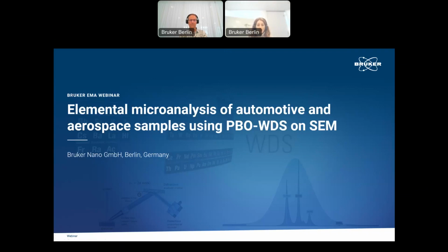In this webinar, we will review the advanced capabilities of WDS to support the development and quality assurance of materials used for the aerospace and automotive industries. We will explain how WDS is an essential analytical tool when analyzing light and trace elements and complementing the elemental distribution analysis by EDS. And why with a WDS detector with grazing incidence X-ray optics, we can enable measurements at low probe current to achieve high spatial resolution, which is essential when identifying very fine inclusions that are critical in cleanliness analysis, for instance.